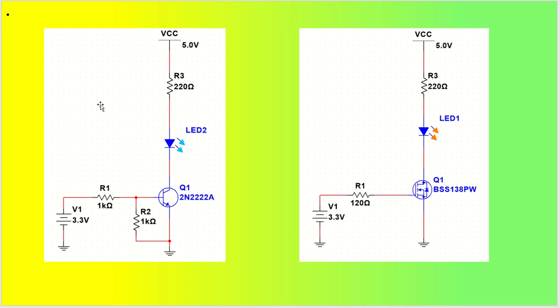So you would have seen, let us say we have an LED and we are driving this by a transistor. What happens is we may require a high amount of current, and that current is not able to be supplied by the microcontroller. Let us say you want to connect a microcontroller directly with one resistor and one LED. The current that will be flowing through this may not be able to be supplied by the microcontroller GPIO. So in those cases, we try to drive this particular LED through the power source, and we use the microcontroller as the enable signal.